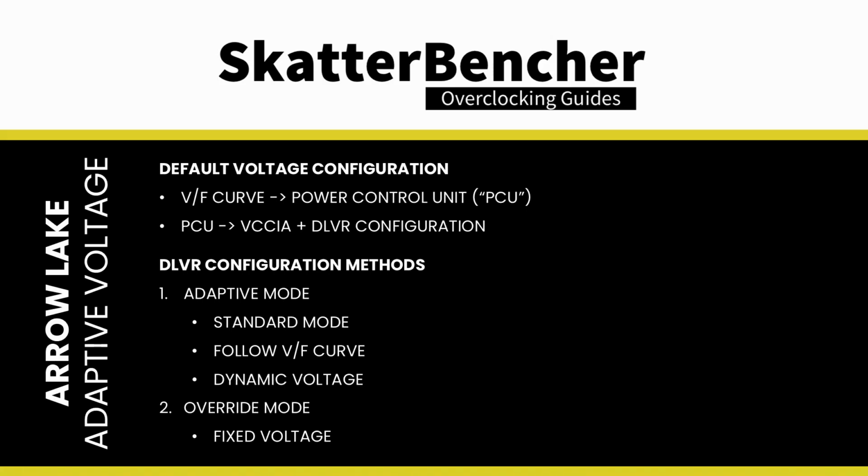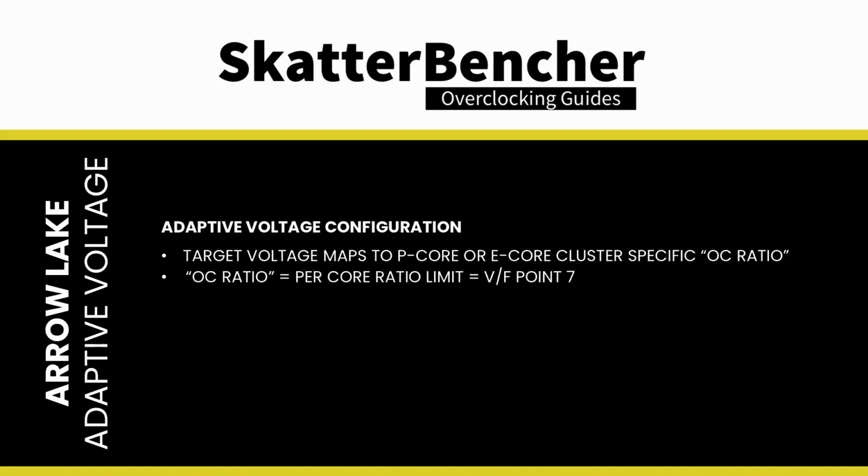We can configure override and adaptive modes directly in the PCU by specifying a target voltage and a voltage offset for each mode. In adaptive mode, the target voltage is mapped to a core's OC ratio. Each P-core and E-core cluster has its own OC ratio, which is defined by the per-core ratio limit. This also matches VF.7.